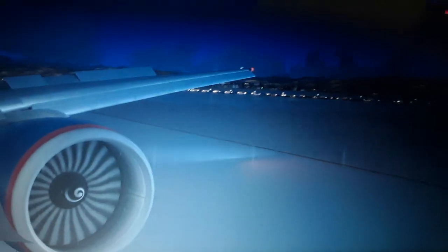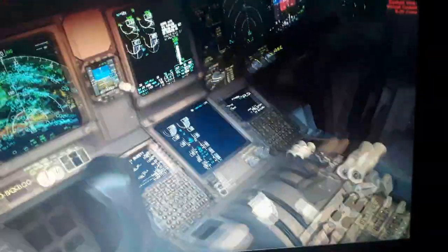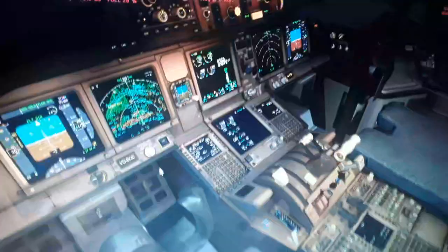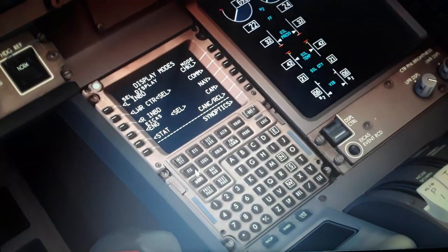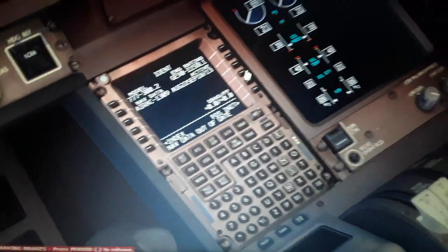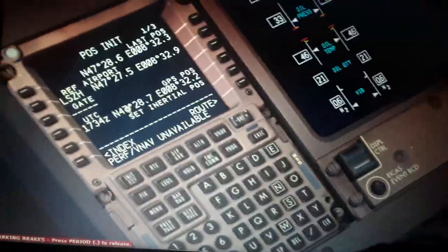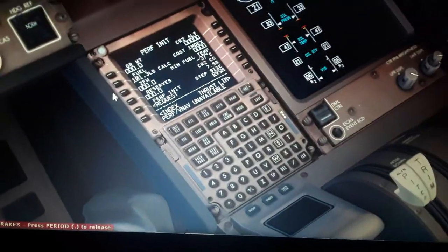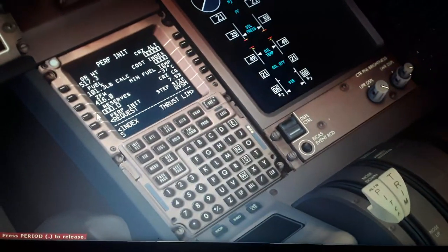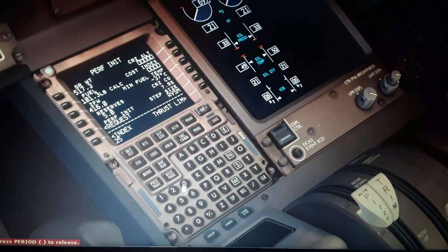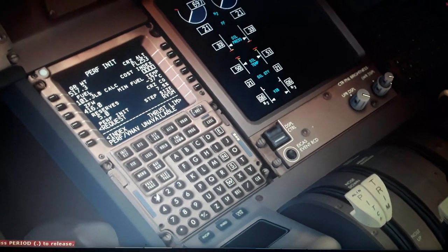Start now, very rapidly spinning, and here we can start. We have only one last step, very fast: the flight management computer, the FMC. You can see the model, the position, initialize LSZH, the reference airport, and the GPS position here, the inertial reference position, the coordinates of the aircraft. Inertial, zero fuel weight, gross weight, fuel on board, calculation, reserves 5%, and cruising altitude 35,300 feet, 100% the cost index like this.